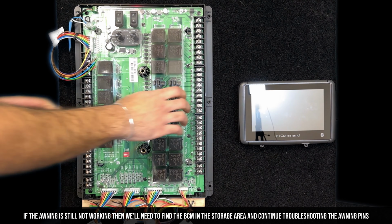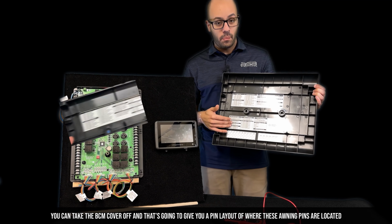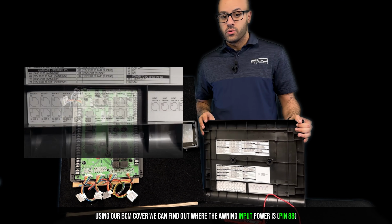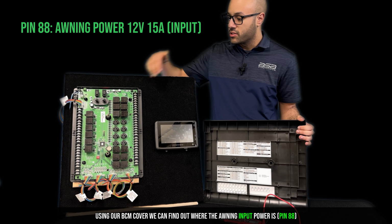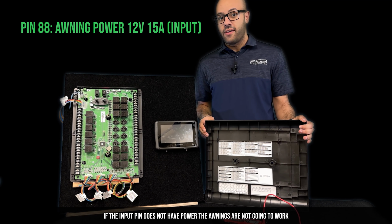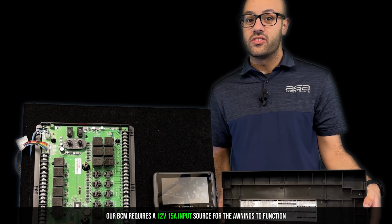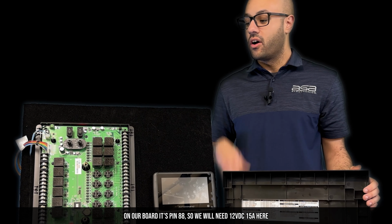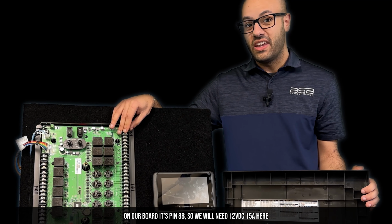the awning pins. You can take the BCM cover that we took off earlier, and that's going to give you a pin layout of where these awning pins are located. So using our BCM cover, we can find out where the awning input power is. That's right here. If the input pin does not have power, the awnings are not going to work. Our BCM requires a 12-volt input source for the awnings to function. On our board, it's pin 88. So we will need 12 volt, 15 amp here.